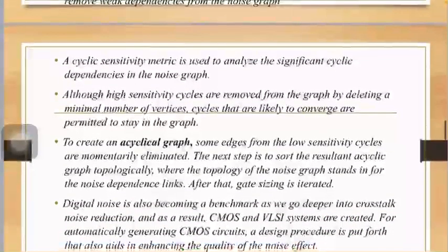So after studying the circuits with different segments, our noise graph is made, which shows where the crosstalk voltage is high and where the crosstalk voltage is low, where it is negligible. So after studying the graph, it becomes easy to devise a solution.